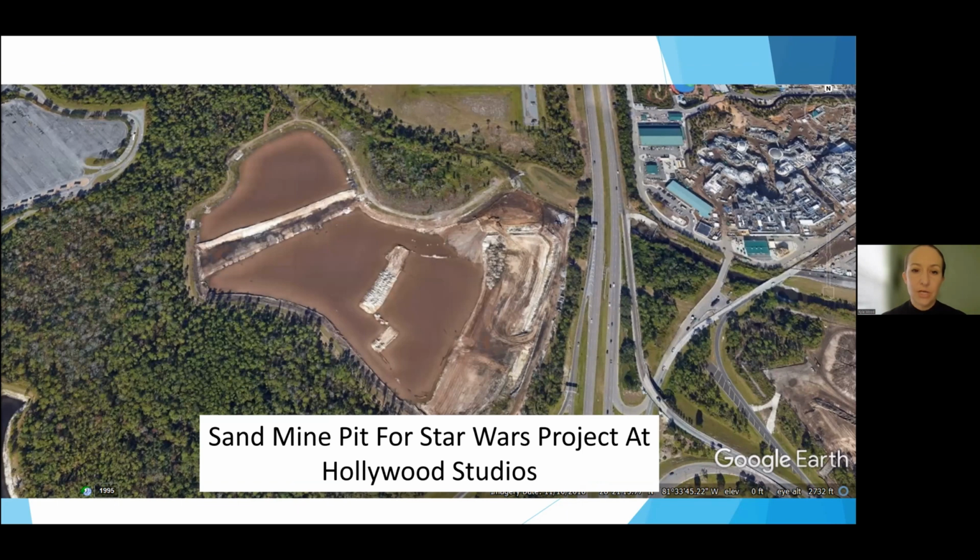So we have this large sand mine pit. At one point, they had done an alum treatment that was relatively successful, but then they had a large hurricane come through and stir all of that particulate up. There was a lot of flooding. They lost containment in the pond, and with alum, if there's a lot of mixing, it resuspends.